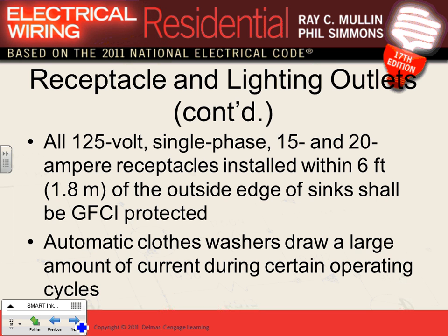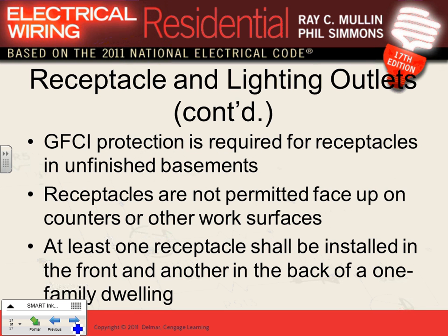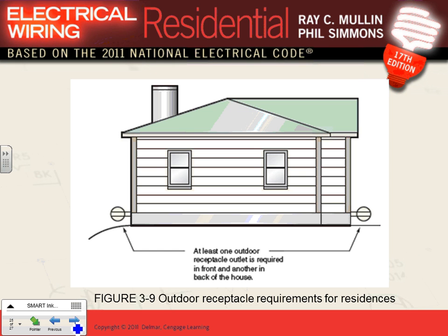Okay, so we got the receptacle layout. Receptacle outlets. We talked about the sinks. Automatic clothes dryers draw a large amount. We talked about the dryers having GFCI. Unfinished basement, we talked about this. 1 in the front, 1 in the back.